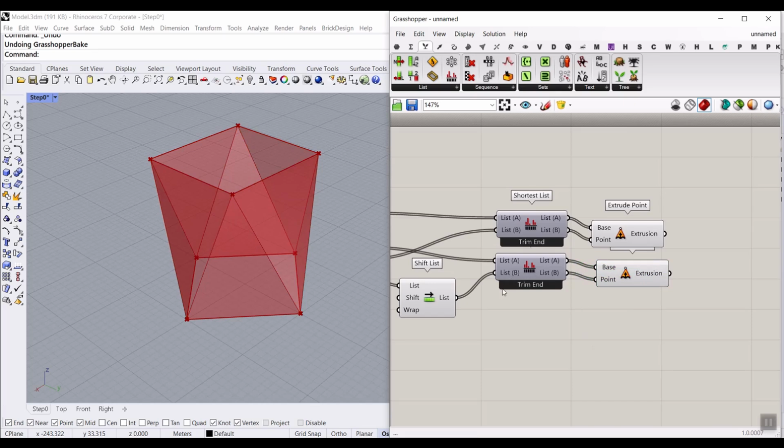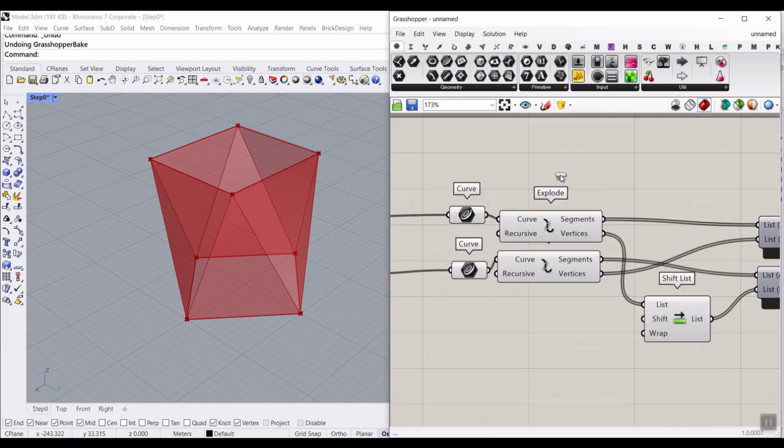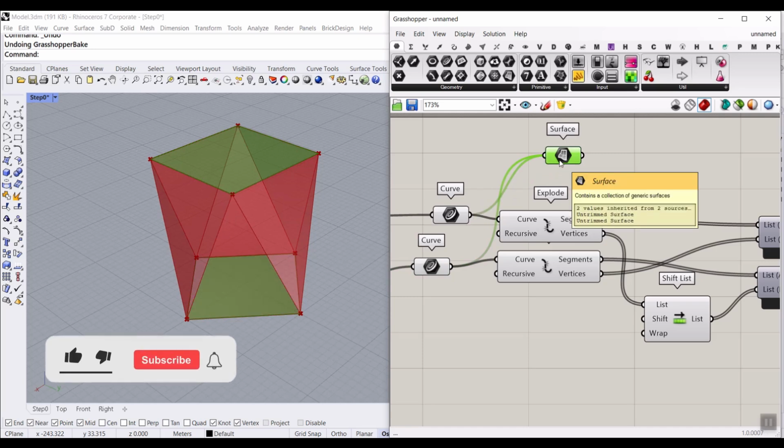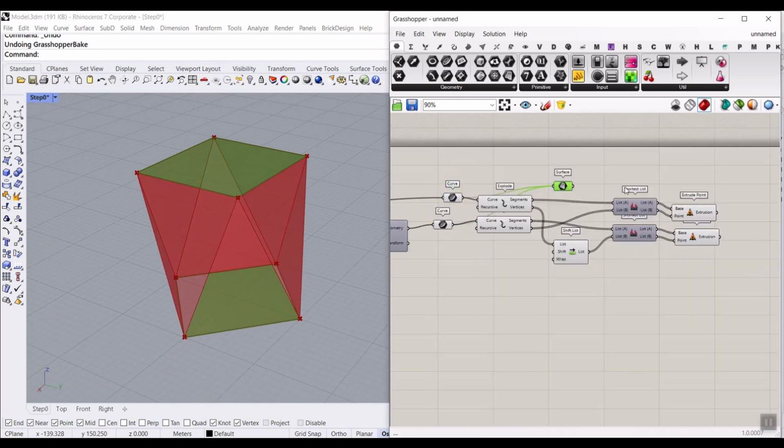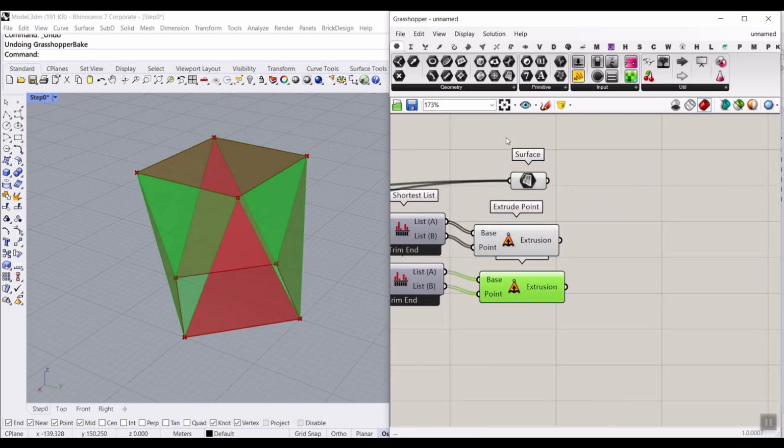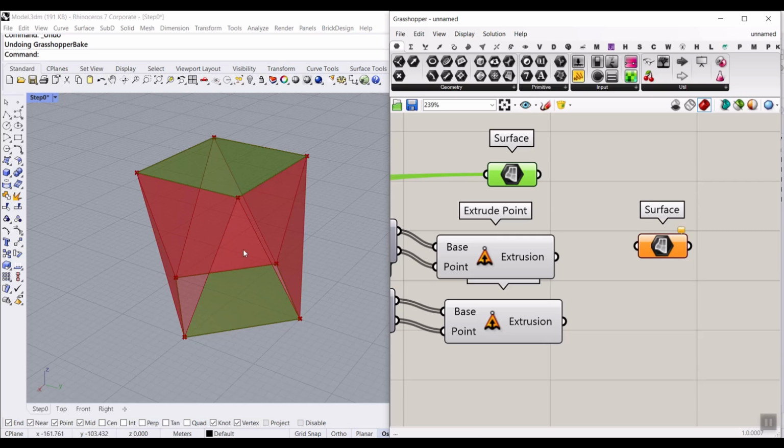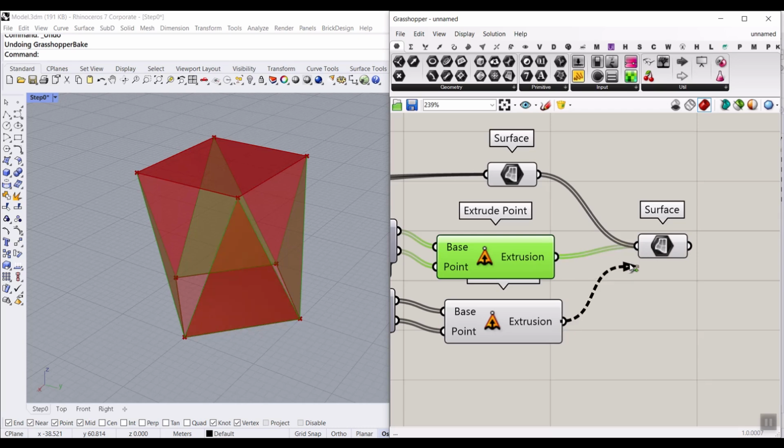Okay. Now let's make a solid. I'm going to go to the params menu and give a surface to both of the bottom and top here. Just a small technique I want to explain. What if I give the top curve first to the surface and then give the bottom? That's going to help us to put the top at the 0 and then the bottom to 1. Okay, that's a small technique I wanted to explain here. And then add the extrusions to, let's just put that all in one surface. So I'm going to say, okay, top, bottom, 0, 1, and then use the shift key, add the first set of faces and the second set of faces.